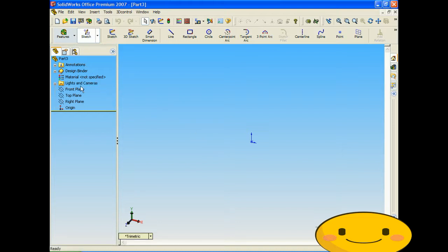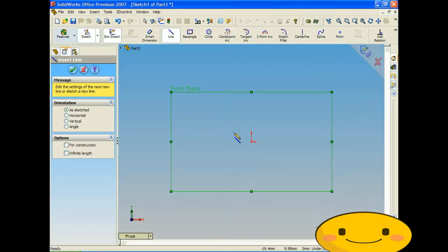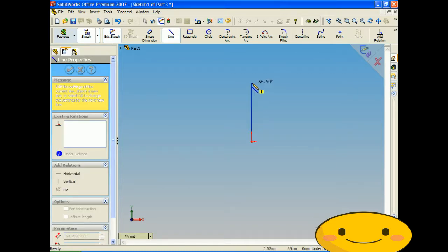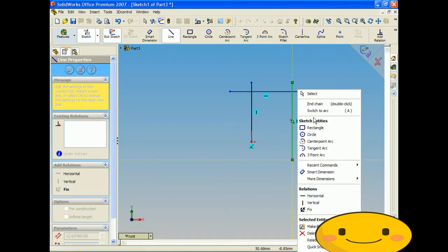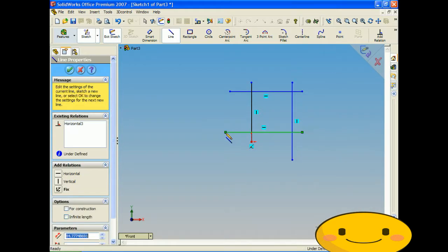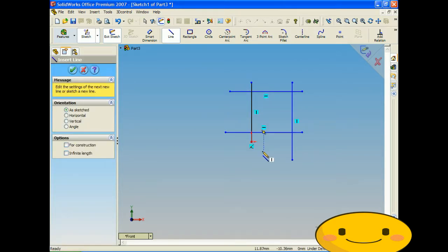So click Sketch, click Front Plane, click Line, and what I'm going to do is I'm going to draw a square, but every line is going to be running past each other one, like each of the other ones. So you can follow and you can make your own just like this. So you can see that at each corner, the sketch runs past each other. So what we would want to do is bring this point here, and do that for all the way each corner. So this is just a more simpler example of what the Trim Sketch will do.